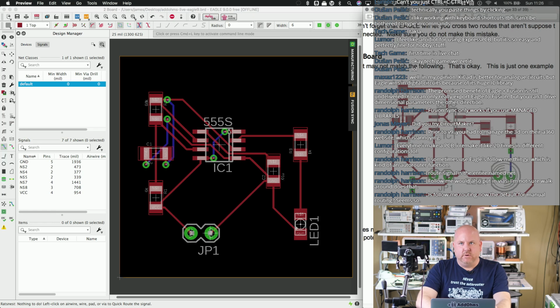especially for lower cost PCB operations, putting vias underneath components can be dangerous because now, well, let me back up. If you're going to hand solder, it's probably not a big deal. But if you're going to do any kind of reflow soldering, even with a toaster oven, what you want to be careful of is a via underneath a component, whether it's a chip or a resistor or capacitor. That via, if it gets any solder mask inside of it, or when it gets electroplated and tinned, that solder that's in the via can actually bubble up a little bit and create a bump.